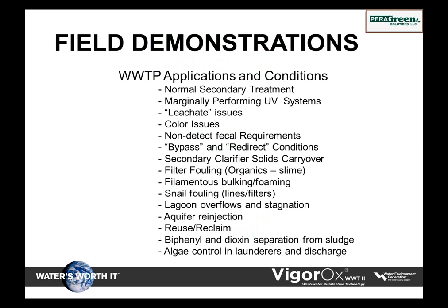Now, just to let you know that PA isn't simply applied, where you put it in there and it kills the bacteria or pathogens or viruses. There's a lot of other factors that influence the reactivity of PAA. The way we approach a facility is we want to know what the incoming chemistry is of all the waters coming into the facility, what impacts that, what are the hydraulics of the facility, what's the design criteria, what are the design maximum parameters that we have to work with.